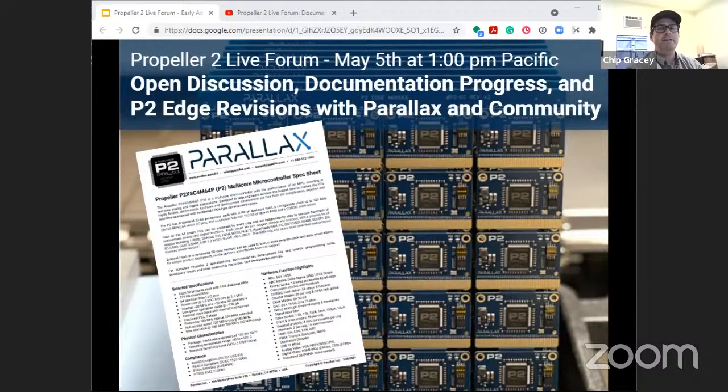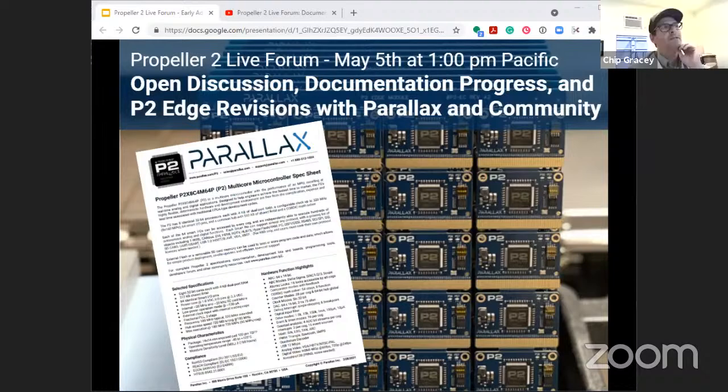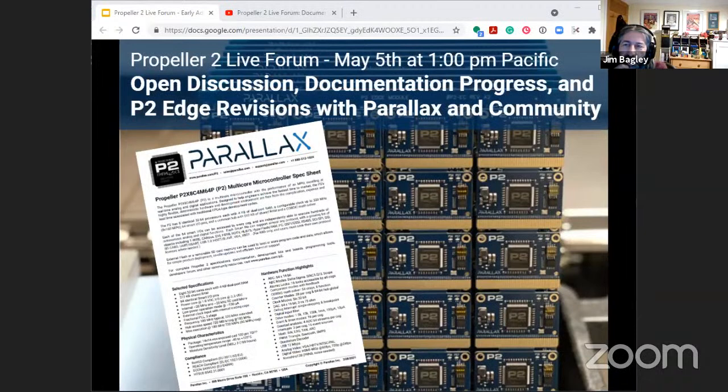I'm forgetting, did you use XByte on that? No, I didn't. The reason I didn't use XByte on that one was because it'd probably speed it up, but with it being Z80 and thinking ahead, because I know a lot of the games and how they work and the bank memory, I needed to have access to the read and write of the RAM. Some of the arcade games have to be able to read a 1K chunk all from the same byte, like a joystick port or something, but it can address any area in 16K. So I wanted to be able to call a function to read a byte from RAM or to write a byte to RAM, with some filtration. Yeah. You could do it with XByte, but you'd have to work around it because the call will cancel the byte skip, won't it, as well?